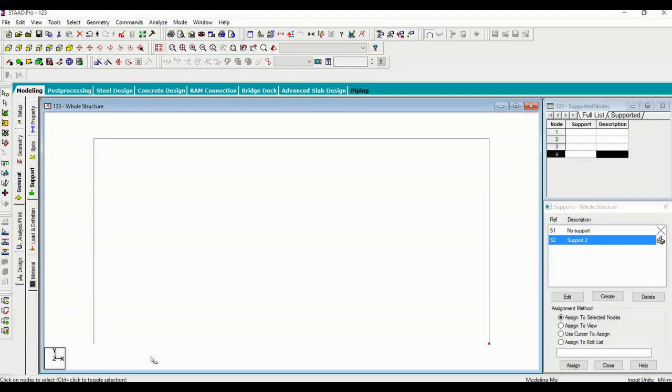To keep both the first and fourth, after clicking the fourth node I should hold Control and click on the first node. Then both nodes will be selected. If you don't want to follow that pattern, you can just use your mouse and select these two nodes.